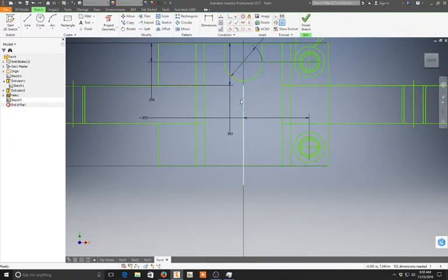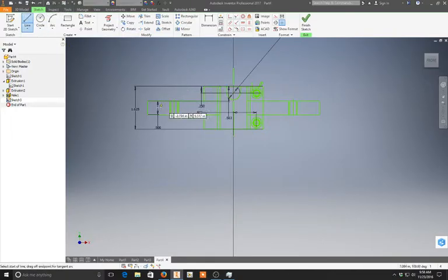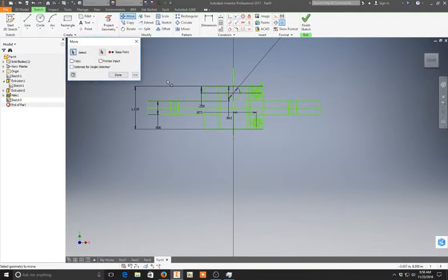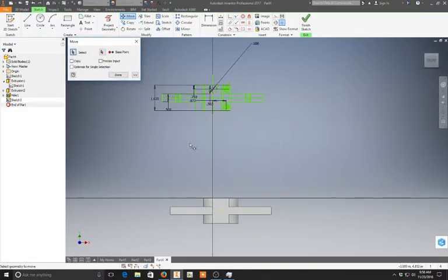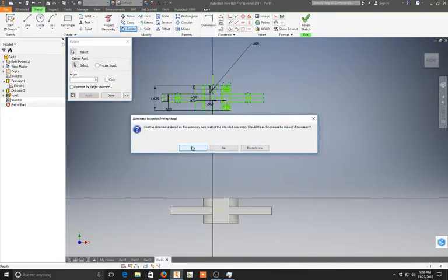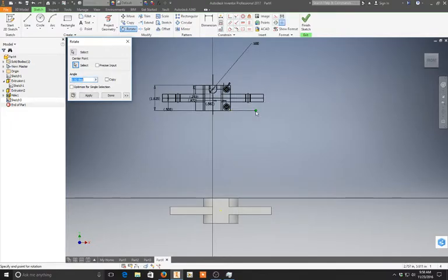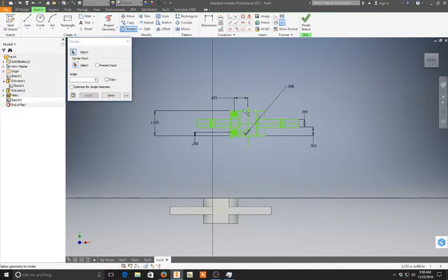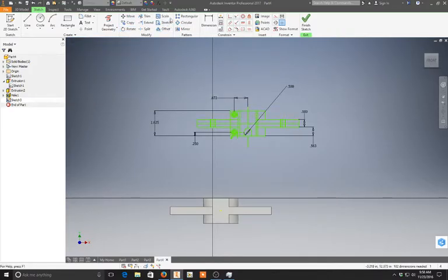So we're going to need a center point right there to snap to. So I'm just going to make this line right here. So now we have a little intersection there that we can work with. And I'll just say, let's see, I need to rotate this as well. So let's rotate it first. Click on the whole thing, center point. Doesn't matter, I'll just rotate it around that. Let's just say 180, see if that works. It worked. Always great when things work.